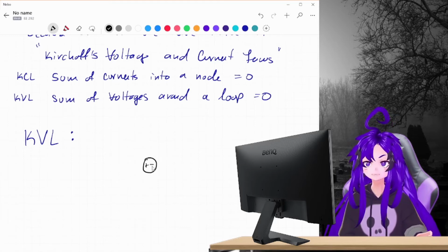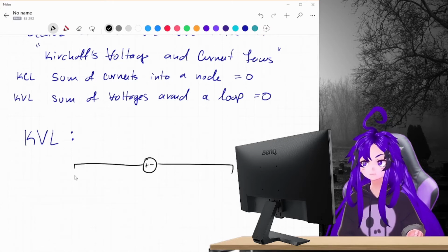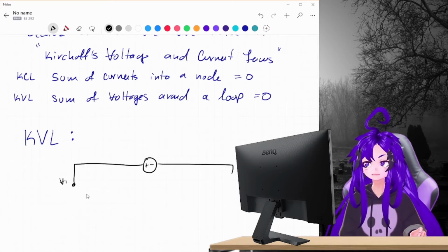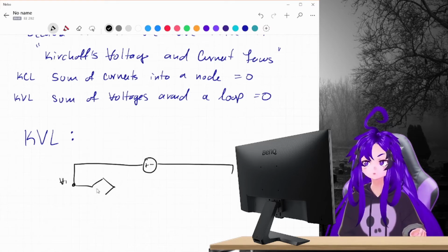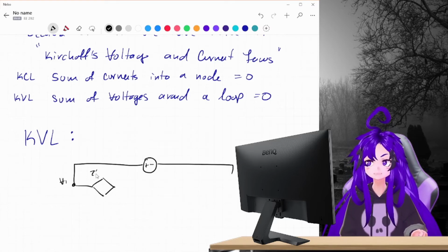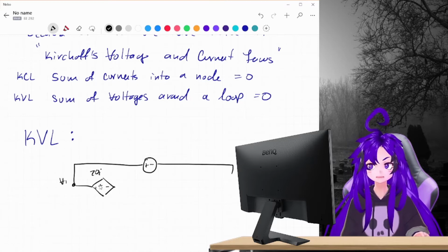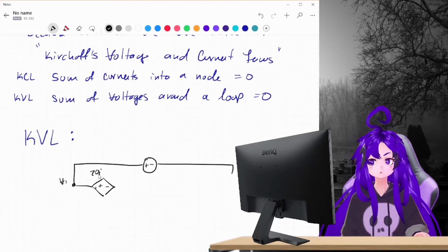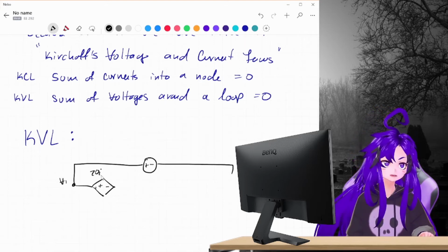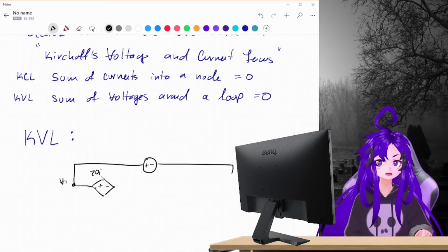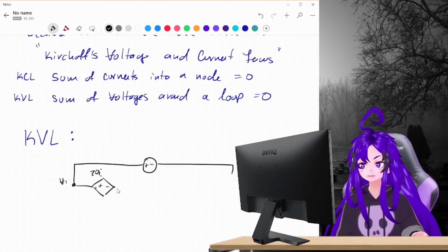So that is the voltage source on top, down to V1, across to the current controlled voltage source. We know it is a voltage source because it's indicated with a plus minus. We know it is current controlled because its characteristic value is given to us as a function of some current somewhere else in the circuit.